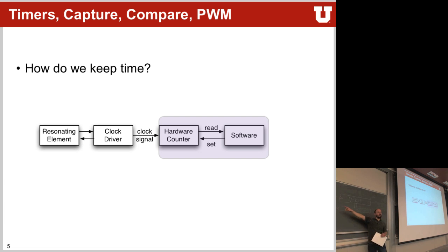The capture will capture what's in here right at this time. And that does not mean that it was the one before or the one after. But you can deal with that with logic that comes in front, making sure that the capture can only capture this value when it is stable, right?